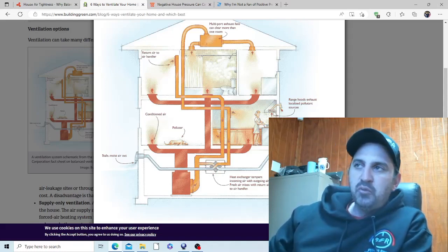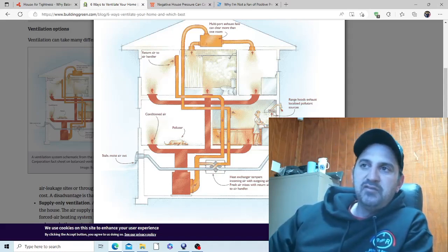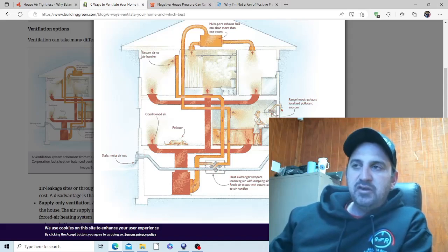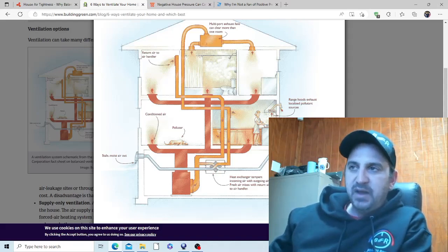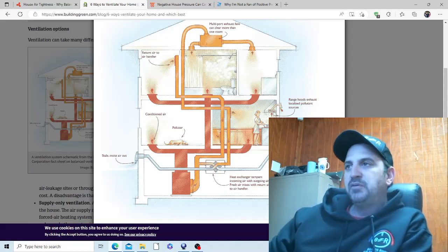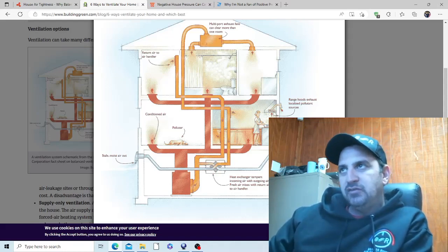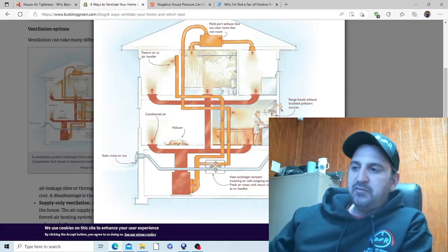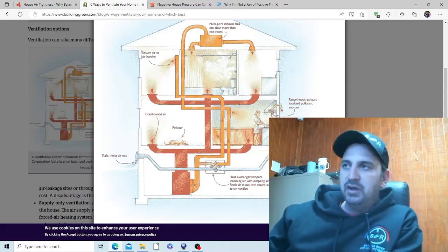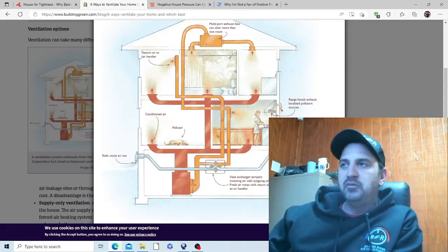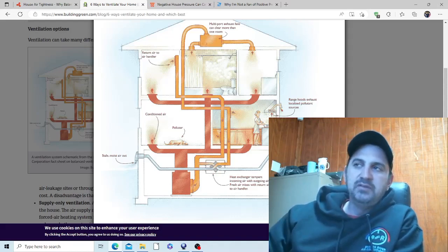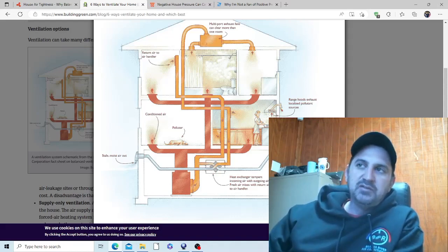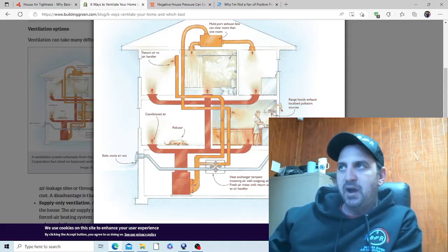This is because they're wiring them in with their rough-in, and a lot of the time it's easier for them to just throw them up and wire them in than worry about where we're placing them as HVAC professionals. I'm changing this on our custom homes, and I'm now trying to supply the bathroom fans, and the ones that we're using are a quieter, more efficient model, which is always nice for your homeowner. They don't want to hear the fan from the next room. They don't want to use a whole lot of power.